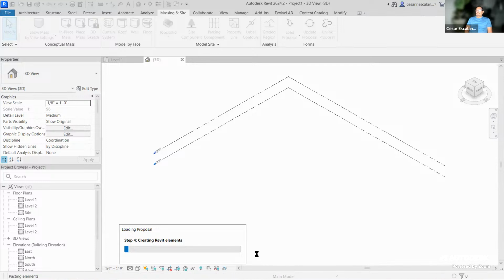If you decide to use this in a project, you really just have to set one project and have one person create the model for everyone, and then enable work sharing so that the rest of the team can contribute to the documentation process. Right now everybody's doing it at the same time, assuming that at some point you might start a project again.